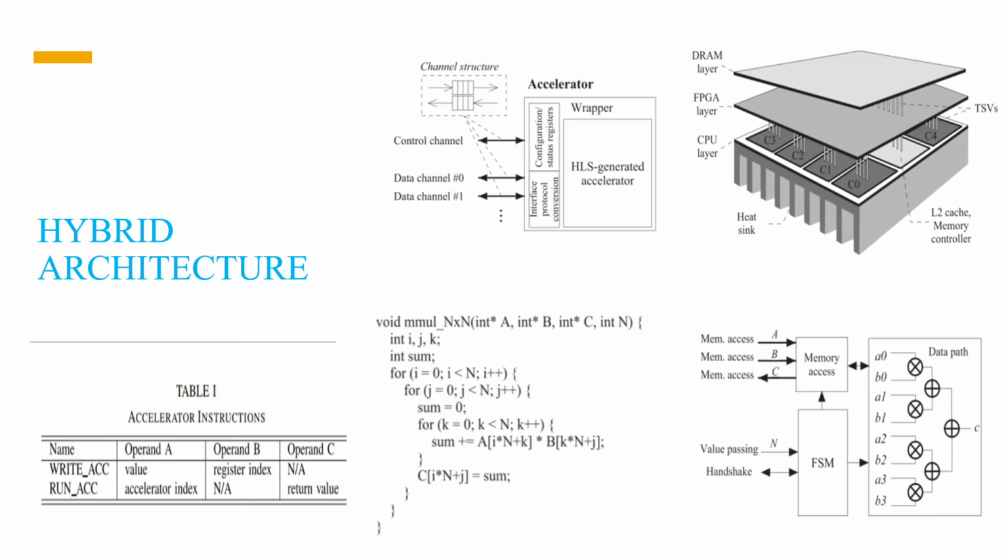Such a design has several advantages. 1. The accelerator can use the existing infrastructure, including the CPU memory hierarchy and memory controllers, which saves hardware resources. 2. Cache on the CPU layer can exploit memory access locality and increase accelerator performance. 3. Sharing cache provides a uniform view of memory space among the CPU cores and accelerator. 4. Sharing cache eliminates the need for copying data, enabling fast switching between the CPU core and an accelerator.